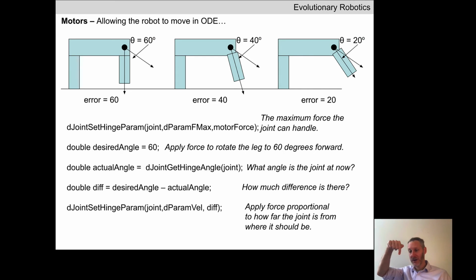So you can get a case where the front leg or an object overshoots and then comes back and starts to oscillate at lower and lower amplitude around the desired angle. And that kind of vibration is probably not something that you want. Imagine an industrial robot arm that is trying to reach out and weld a car door in a factory. Imagine that it slams into the door and then pulls back a little bit, goes forward, hammers the door again, bang, bang, bang, bang, bang, and eventually comes to a stop and then starts to weld. You can imagine that's very bad news for the industrial robot arm and probably for the car door as well.